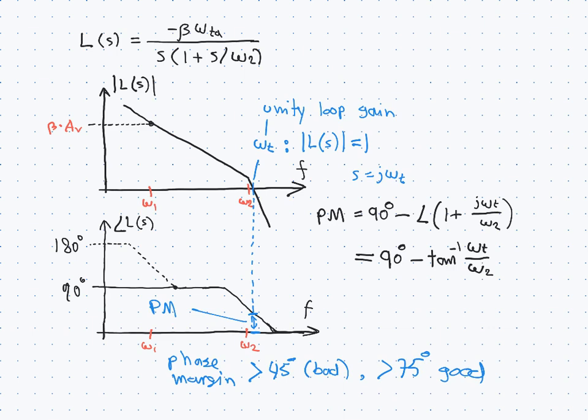So the borderline of the second order pole is that it sits right at the unity loop gain frequency, which means that in general this drawing is not so good. It's not a good system because the second pole sits at a frequency which is lower than the unity loop gain frequency, and it should be moved up to a higher frequency to have better phase margin.